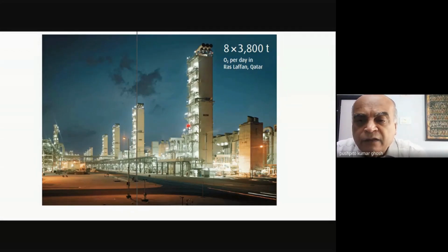On the other hand, if you are trying to recover both nitrogen and oxygen, and especially if you are trying to recover it in liquid form, then there would not be that much waste available to cool the incoming gases. Naturally, in that case, the energy consumption will be more, because proportionately you have to do much more of the Joule-Thomson expansion to get to those cryogenic temperatures. But it is the air separation to get both nitrogen and oxygen which obviously has been of great interest.